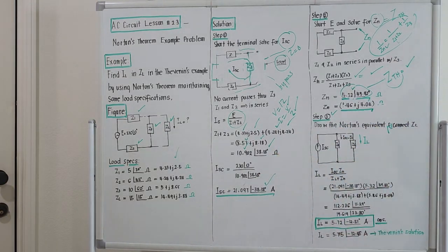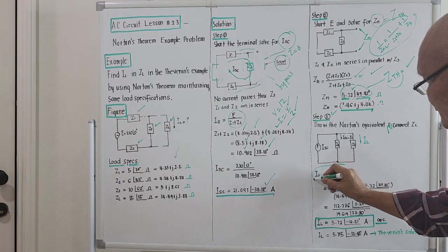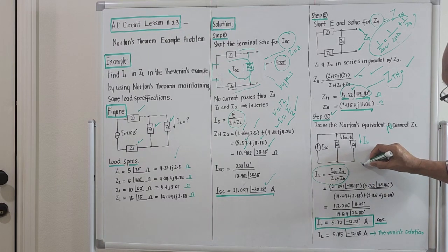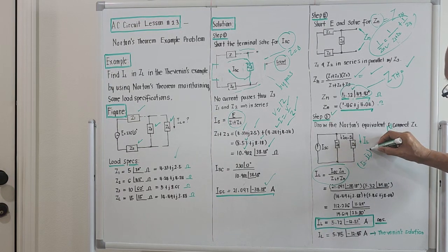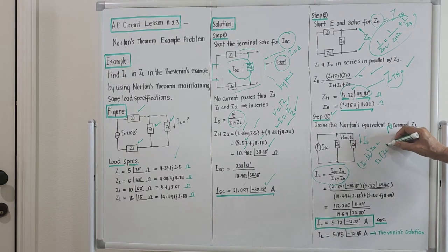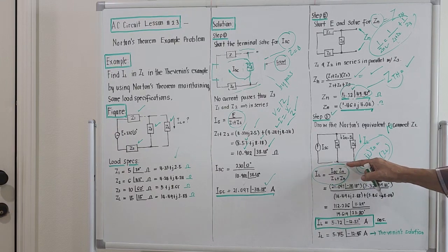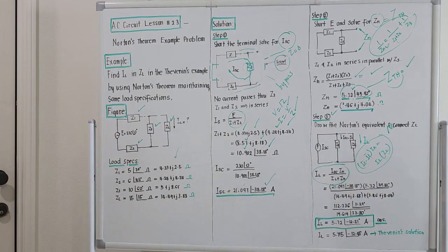So if we try to reconnect, it seems C sub n and C sub L are in parallel. We derived this one already. Because to derive this one, it will be the product I short circuit minus I sub L multiplied by C sub n should be equal to the product IL times CL. If we try to simplify this one, combine those, IL now will be the product I short circuit times C sub n over the sum of C sub L plus C sub n.